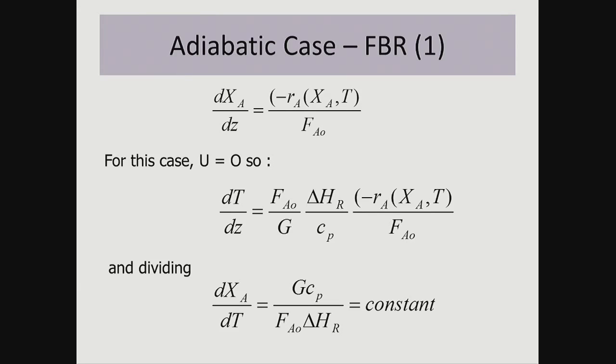You've got the mass flow, you've got the heat of reaction, which you should be able to have found from somewhere, and the heat capacities, so you know what the change in the mixture is as it converts to something. Does it gain heat or does it absorb heat? So therefore, is it an exothermic or an endothermic reaction? And then you've got the rate, which is a function of conversion and temperature over the flow rate as well. So you can see that turns into that.